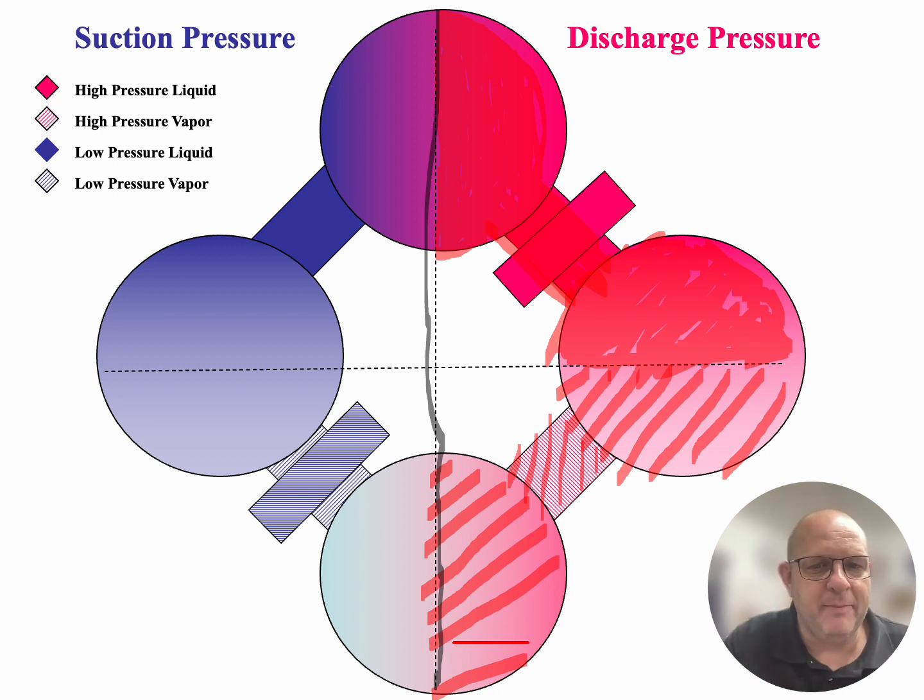So it goes through that metering device and then it expands. And when you expand a gas out, or a liquid out, into a very large area, that vapor will drop in pressure and then will drop in temperature so that we can absorb heat on that metering device. So on the exit of that metering device, we're going to be a low pressure, low temperature liquid.